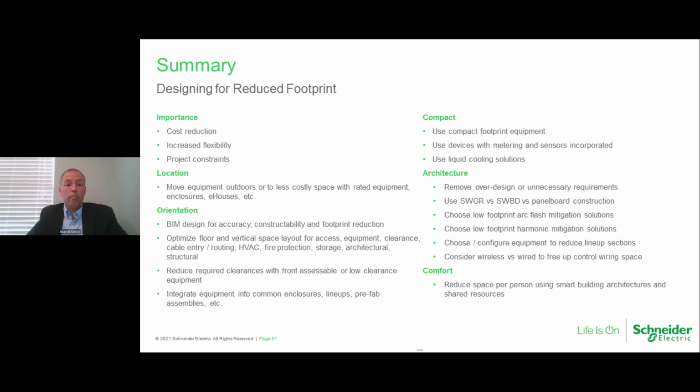and a lot of times a small footprint piece of equipment gives us the ability to work around issues in a site. We're able to, for example, when I was talking about the gas insulated switchgear application, instead of a 200 foot by 25 foot by 50 foot wide 4 split building, we were able to move it down to a 70 by 20, 22 foot wide single shippable building. And especially since with e-houses, it's price per square foot, there was a cost savings, but the big advantage was they didn't know where they were going to put this equipment on their site. They didn't have space.